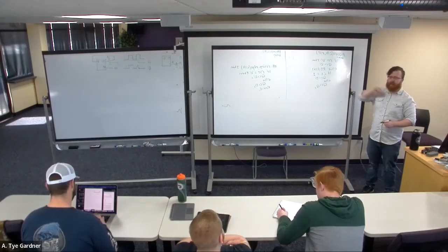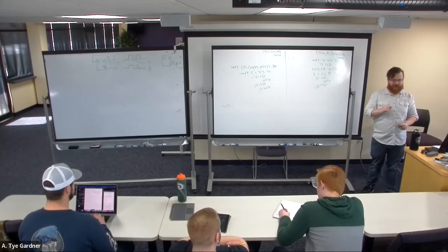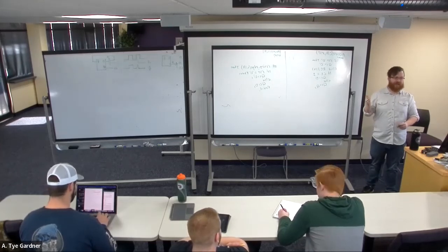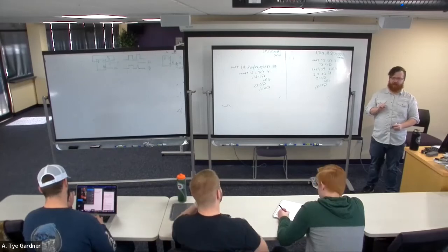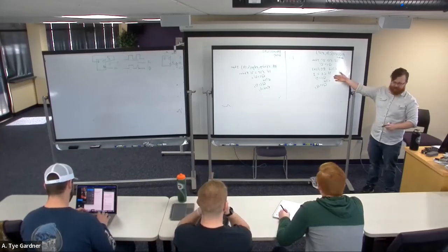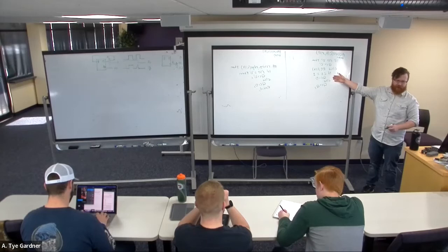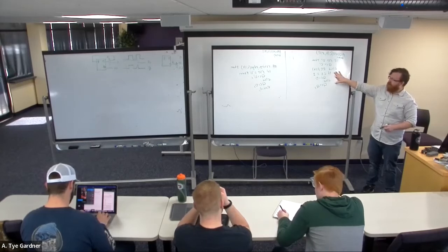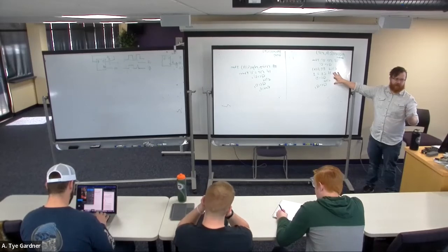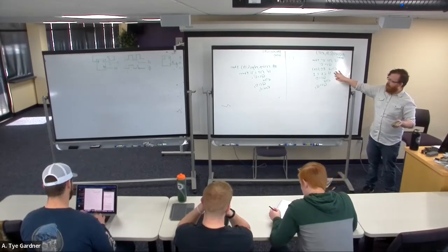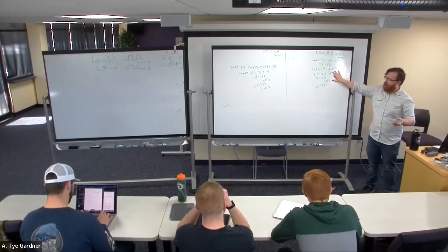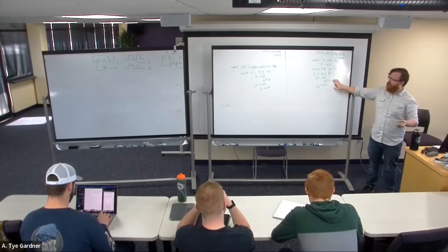This will weirdly build a mux. Even though we know that the when-else statement is a good way to build a mux, when-else's don't work inside of a process because a when-else is a combinational device. This will still build us the same device, it's just a different way of writing it. We have to be careful to understand that the way we write things changes what's happening.